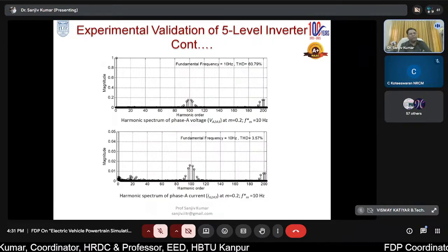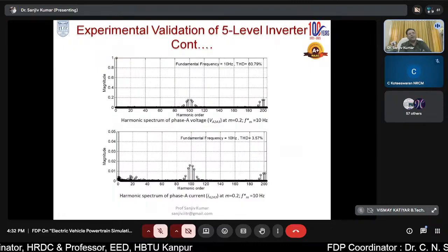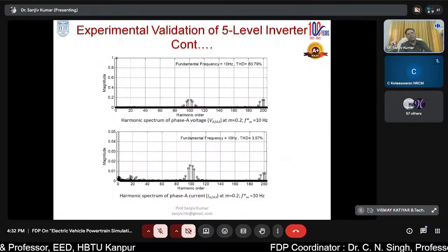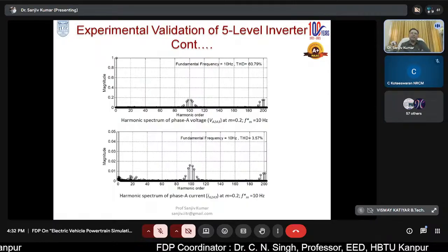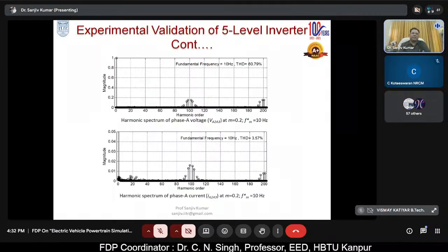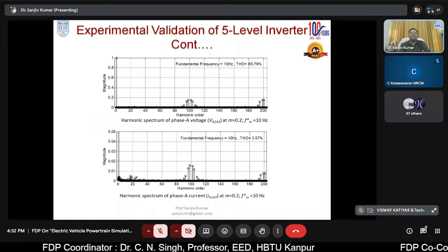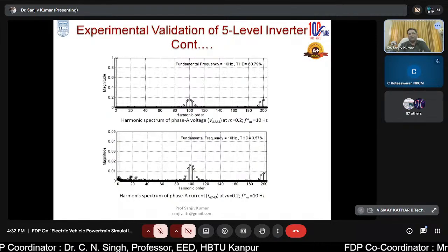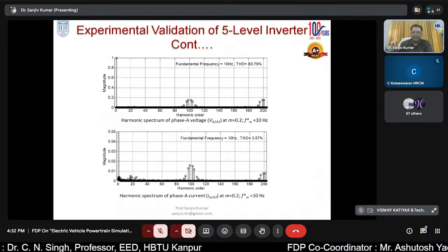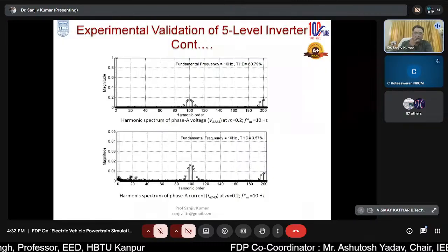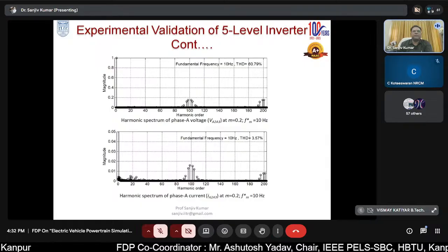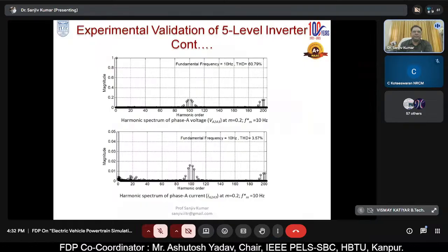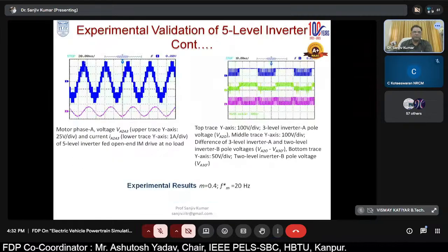We took them from AD202 to the analog input of the OPAL-RT, and thereafter, getting this data in real time from the hardware, we made these graphs using MATLAB. So these are the real parameters which we practically receive in the setup.